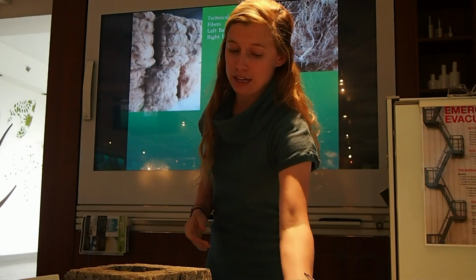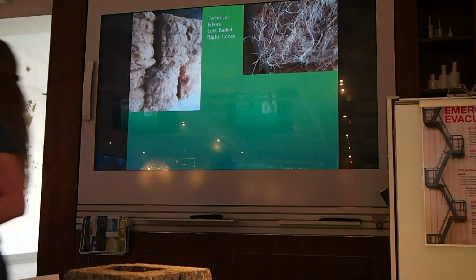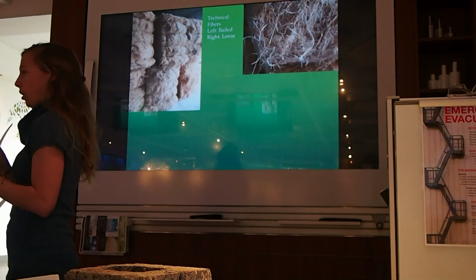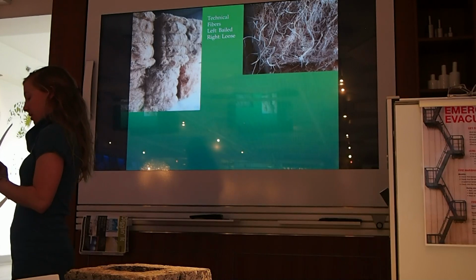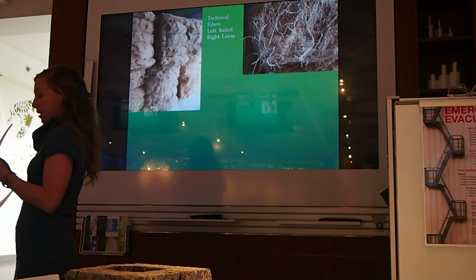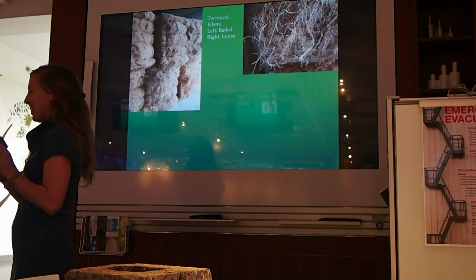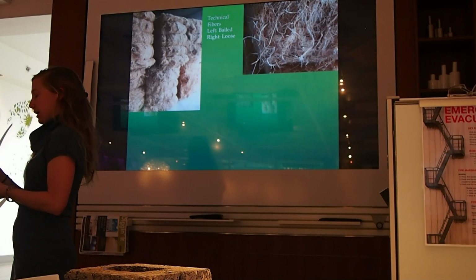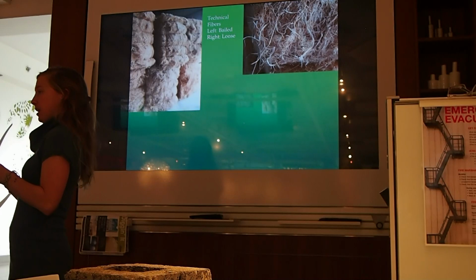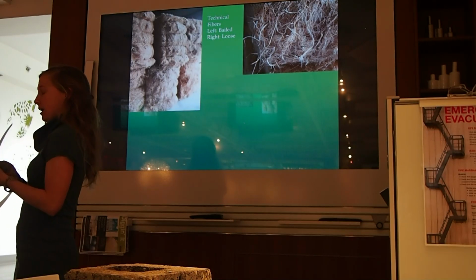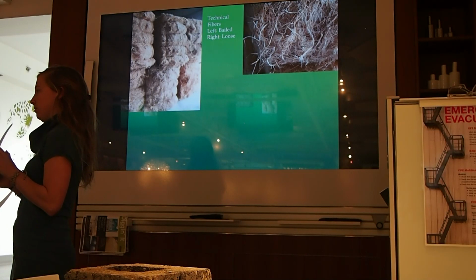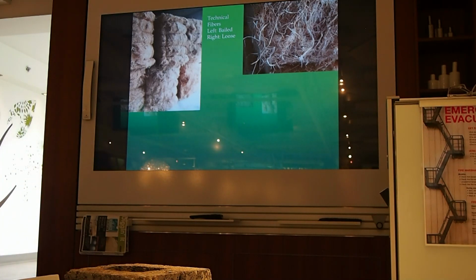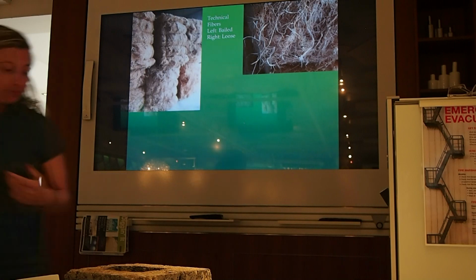He also has a... Can we see that? Yeah. Also has a cement pour. So I don't know exactly what's in it, because he doesn't tell me, but it has the hemp fibers in it, and it is 100 MPa compressive strength, and the pour does not need the use of rebar. So that's another good quality of those products.